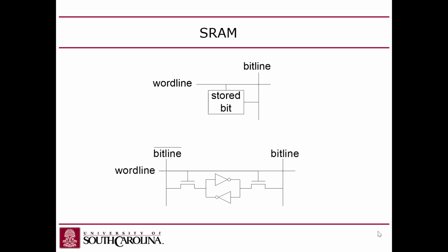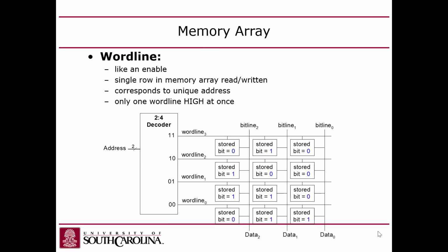if we go back to the decoder, the fact that we take the memory address and decode it into word lines is the reason why, as you increase the size of a memory array, it becomes slower. It's the fundamental reason why we have a memory hierarchy, because if you make a bigger memory, you have to have more word lines. More word lines means a bigger decoder, and a bigger decoder has a longer propagation delay.